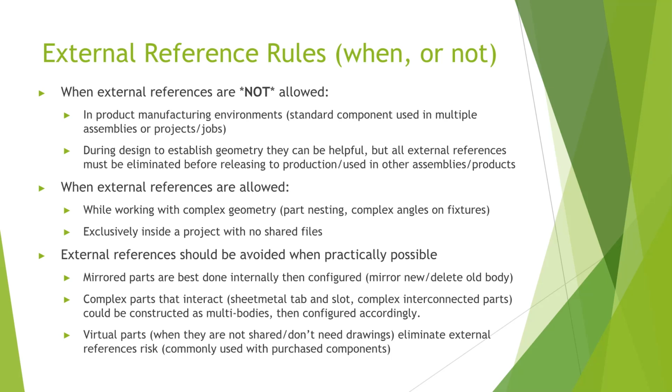So you can do it all in one part file, configure it out, do multiple bodies, run body deletes, configure it out into configurations, and segment them out. You can still have your own drawings. You can still have your own part numbers. There's no limitation on the end of it. It's just how you manage your references.